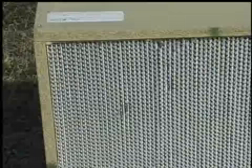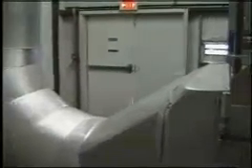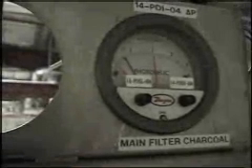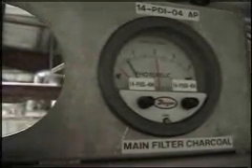The filter unit, which ranges from 3 to 12 inches in depth, is mounted in a gasketed retaining frame to prevent leakage around the filter media. The contaminated gas stream passes through the filter media, leaving the dust cake on the upstream surface. HEPA filters are typically changed when the pressure drop across the filter increases by 2 inches of water. However, HEPA filter systems may be designed to operate with pressure drop increases of up to 10 inches of water.